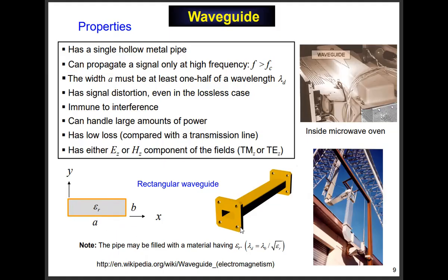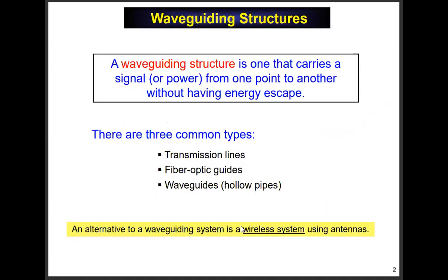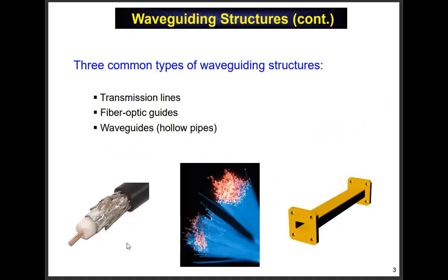Now, what's going to happen in something like a coax? Let's go back to the coax just for a second. Okay. So you've got an inner conductor and an outer conductor. They're both carrying equal and opposite currents. So this one here, the skinny little wire, is going to be the one where it has a huge current density, right? Huge current density. And that's one that's also going to have a lot of high charge on it, surface charge density, very strong electric field around it. Okay.